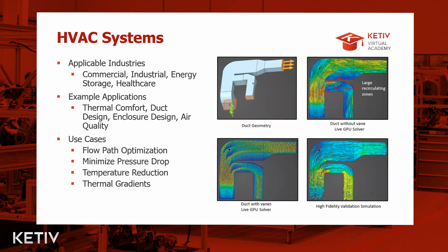And in those cases, when you're doing quick and dirty analysis preliminarily to understand what should be the optimum design configuration, Discovery is the perfect tool for that. You could optimize your flow path, minimize pressure drop, identify hotspots, reduce overall temperature, look at thermal gradients, identify low circulation zones or recirculation zones.